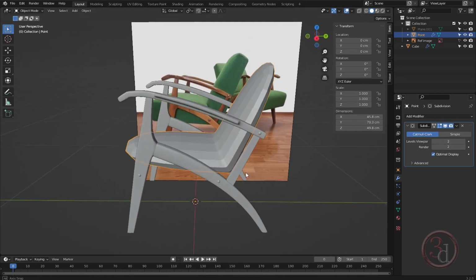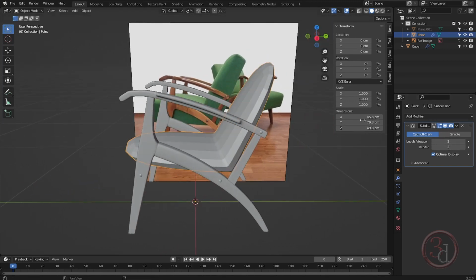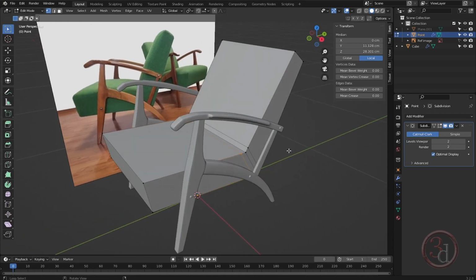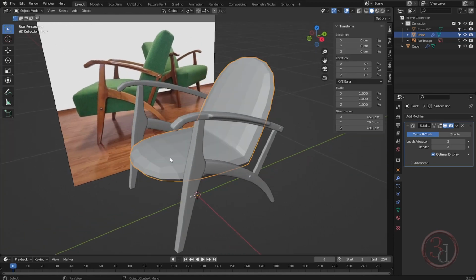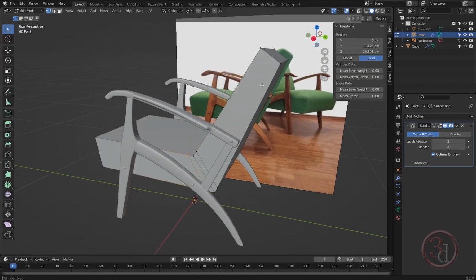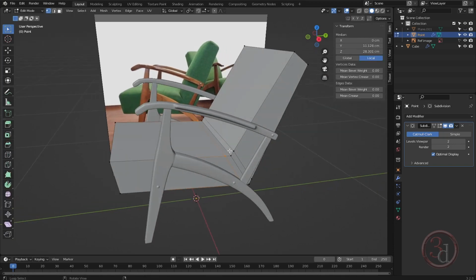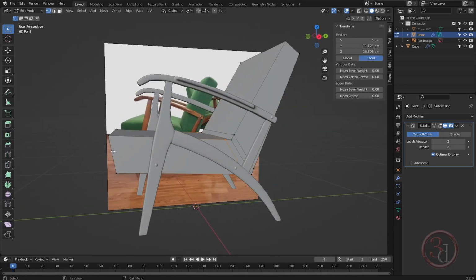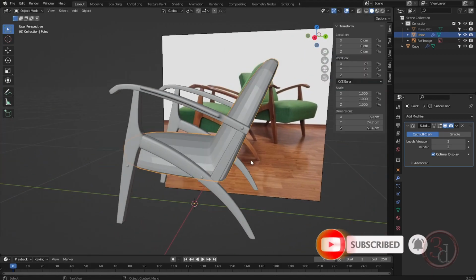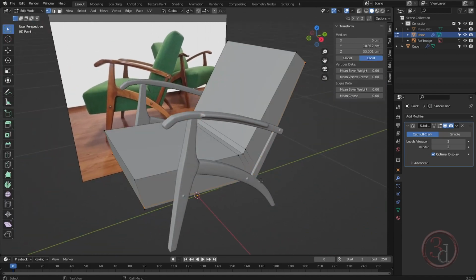We'll add one more level, and now what we can do is I will click this so we can tab. So this is the object mode. If we go into the edit mode, we can see the actual shape, and then we can modify it and see how the result is. So we definitely need a crease coming here, so Control R and then bring your mouse so it will adjust to the direction that you want, and then you can add detail, and then if you press the tab we can see how it's coming. It's coming good.